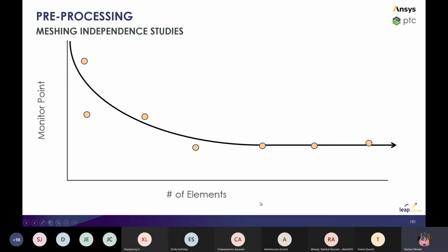So what I normally do is keep something constant, right? So maybe the surface mesh might be constant, and I'll try to make the volume mesh a bit finer, and then start to pick up what's happening around there. If you're interested in what's happening directly around the car, maybe you keep the volume mesh coarse, and then you just make the mesh around the car a little bit finer. Generally, the two things will come together, and you'll probably be making changes consistently between the two of them. But this again depends on what you want to do.